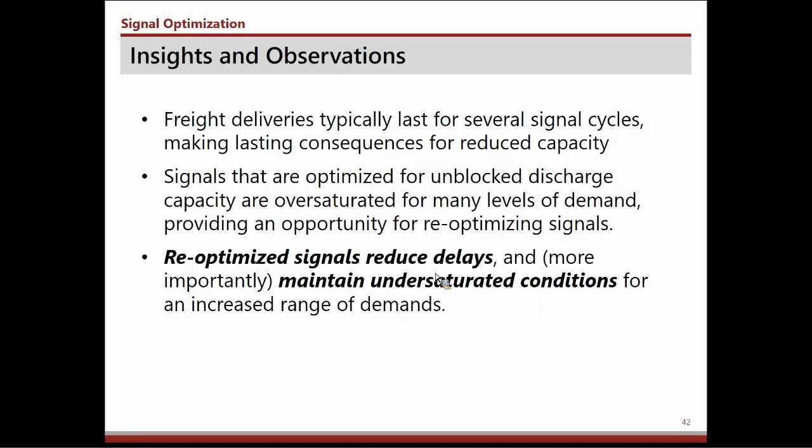And signals that are re-optimized for these, they can reduce delays a little bit. That's not really what we get excited about, but that you can maintain under saturated conditions allows you to clear these queues up, and clearing up the queues is going to reduce vehicle interactions on the roadway as well.